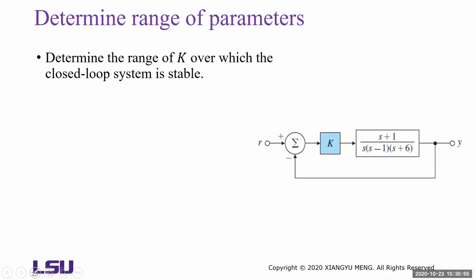To use the Routh array, you need the coefficients. That's why you need to expand it, not factor it, to get the coefficients of the polynomials.